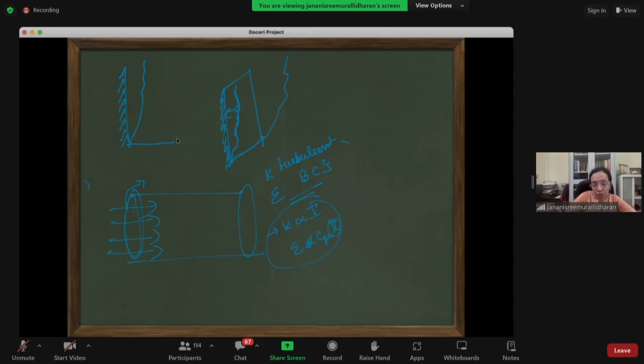Now, as far as natural convection is concerned, you will have to use something called transition turbulence models. They are more accurate. What does it say? If you see your domain, your flow is not turbulent with turbulence injected from the beginning. It will become turbulent after a little while, depending on the force.